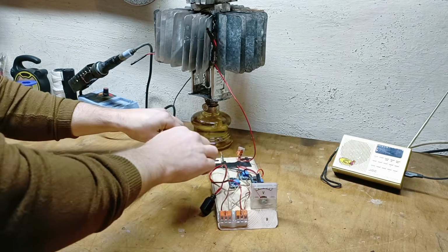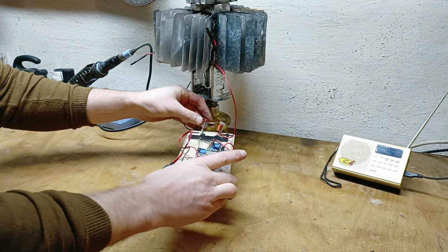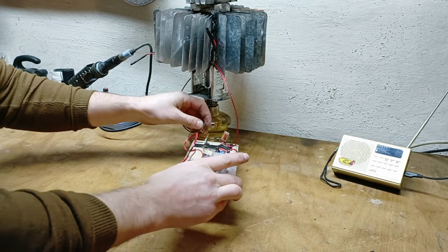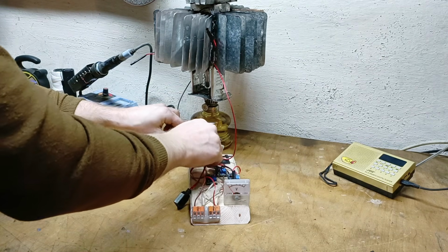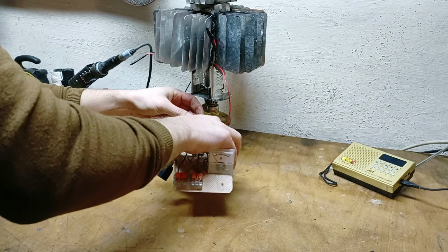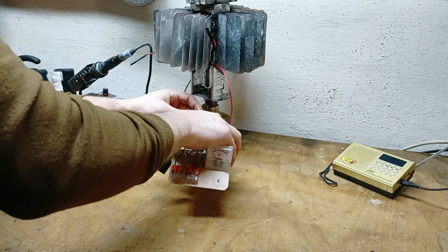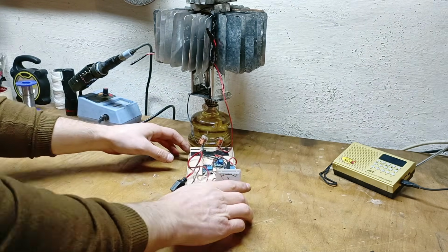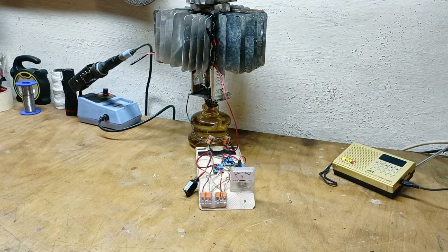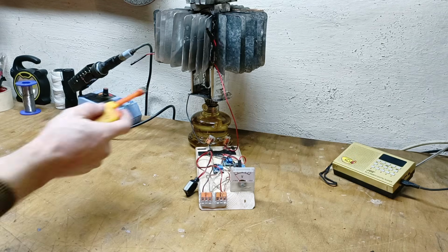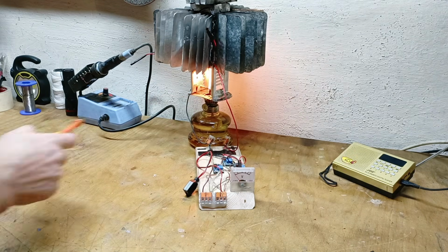Why did I choose a circuit with step-up converters? Because I don't want to overheat the Peltier cells. When I started working on the project, I had 10 cells, but 2 have since been damaged. So, not wanting to risk overheating them again, I decided to reduce the heat supplied to them from the lamp burner, thus saving a lot of kerosene, by the way. At the same time, I didn't risk damaging them again.